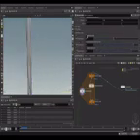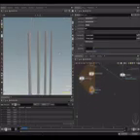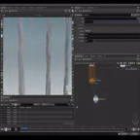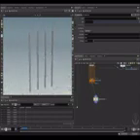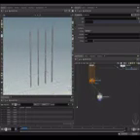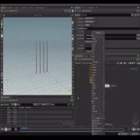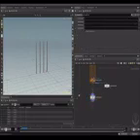Let's turn off this. And let's apply the same detail to every box. And here we go. Perfect. So this is going to be our high-res geometry. So let's drop down an attribute delete node to clean the attributes I don't need anymore, like old position and this wood. No, I'm gonna leave it actually.